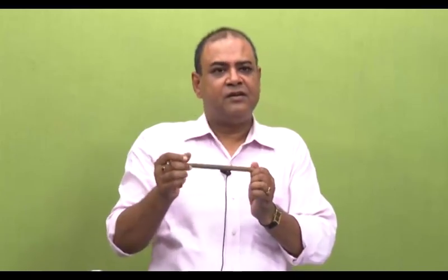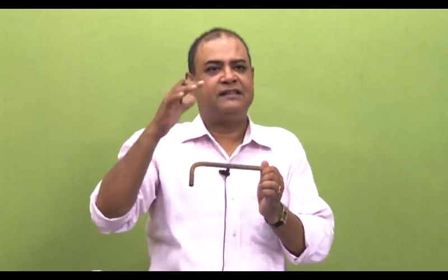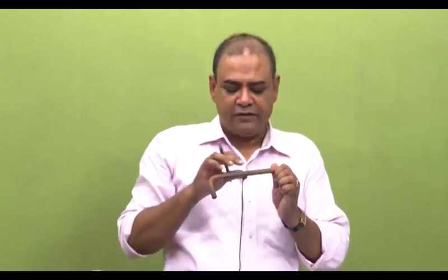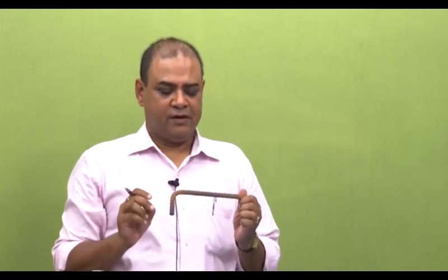There water can deposit and it would stay. This is absolutely stagnant water, and that would lead to higher corrosion. So, that is what you are getting, more red rust at the root of these ribs. Other portions are relatively red rust free. Okay. So, this is one typical example where you can see crevice corrosion.